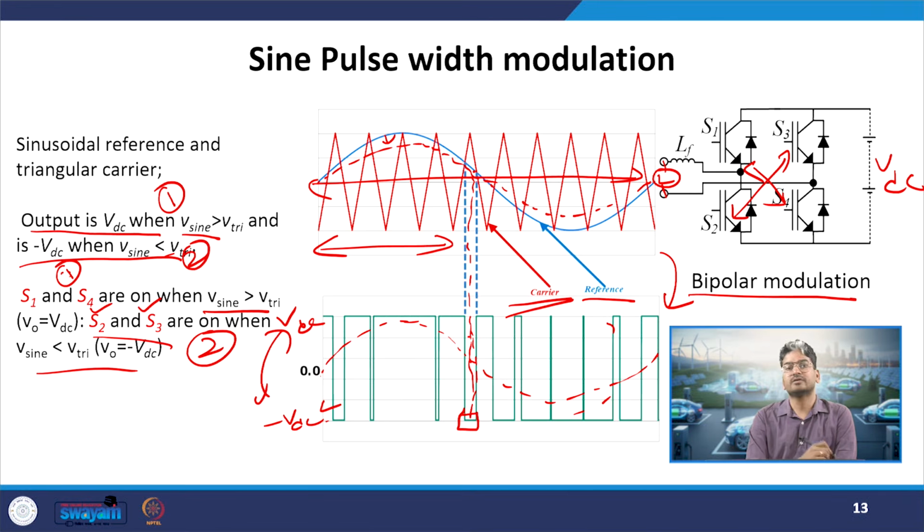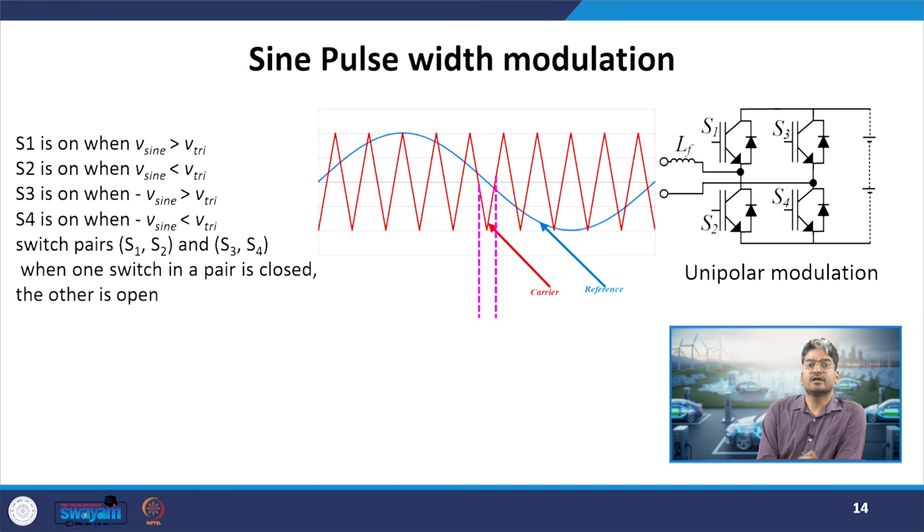So, the filter size is proportional to the dominant harmonic frequency also, or the frequency for which it is designed, or for the frequency which it has to eliminate. If that is on the lower end side, the size will be bigger. If it is on the higher end side, the size will be smaller. And in this case, now let us see the other mode of operation.